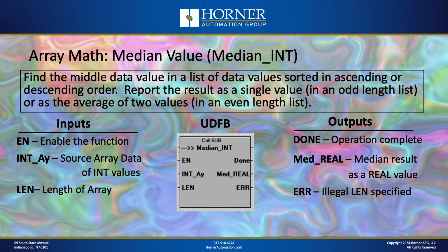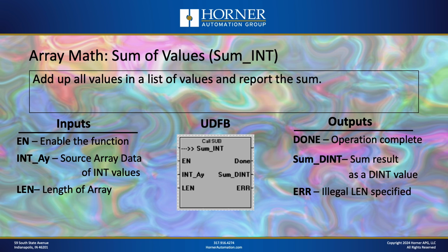Okay, let's start with array math. So what is array math? Well, really, array math are user-defined function blocks that are designed to perform math and statistical operations on an array or a list of data values. That's really what it's all about, okay? And we'll start with median. What is median? Well, median is the middle value in a list of values, either in ascending or descending order. Okay, so this user-defined function block will report back the middle value or the median.